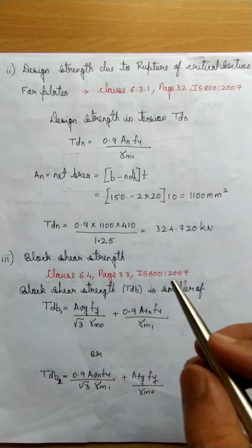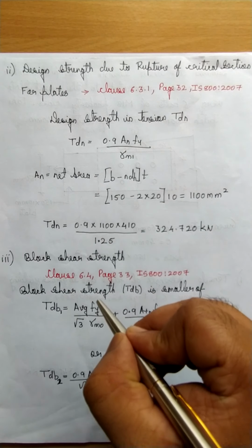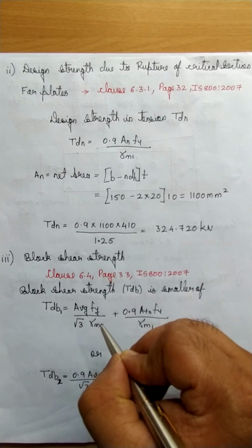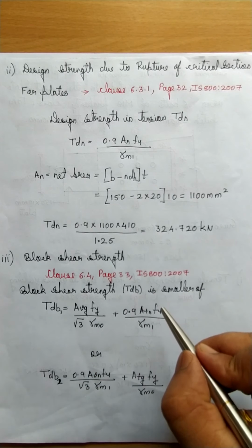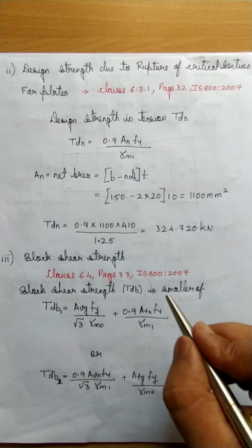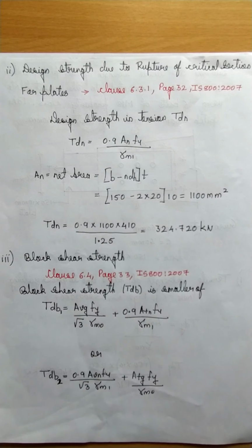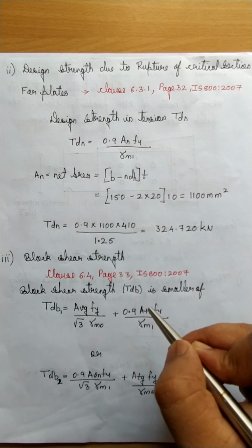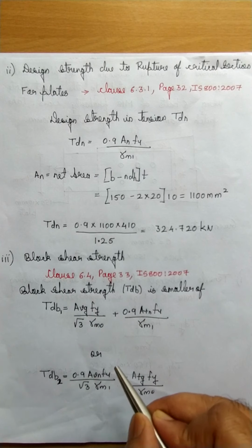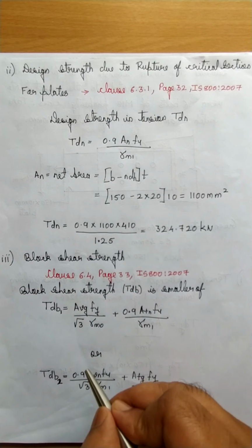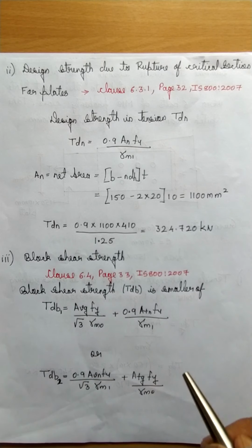Now in this, what all do we know? We know Fy, that is the yield strength of the member, that is 250 Newton per mm square. We know gamma m naught from table number 5, it is 1.1. We know Fu, which is 410 Newton per mm square, the ultimate strength of the plate, and gamma m1 we know, that is 1.25 from table number 5. So the important components which have to be found out are Avg and Atn. Similarly in this also we know Fu, gamma m1, Fy and gamma m naught. So we need to find Avn and Atg. That's what has to be computed.